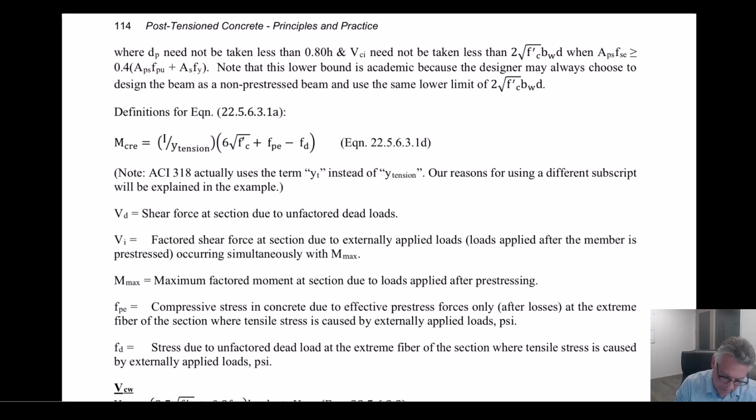And if you realize this is just the section modulus to the tension side. So why the code felt the need to write the moment of inertia divided by y to the tension, I had not just put section modulus in. Again, something we'll never know.